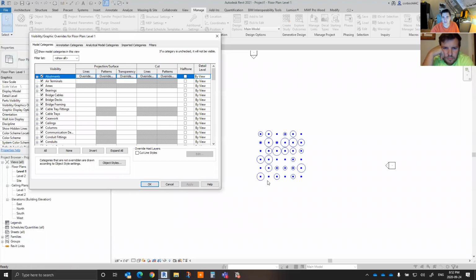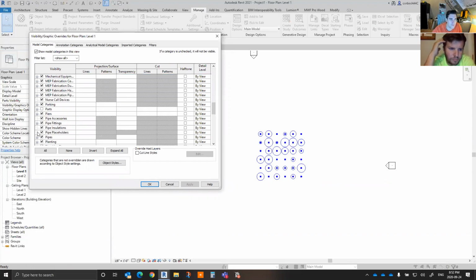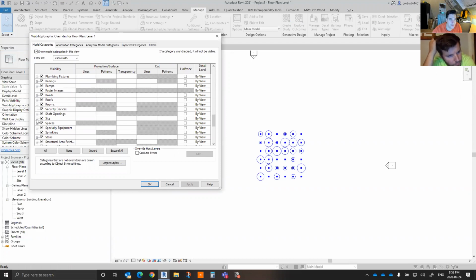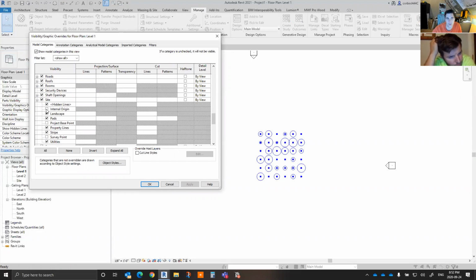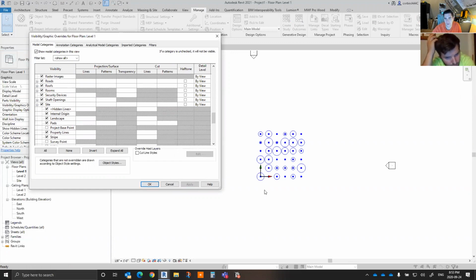You can see where this is starting, and it looks like it's starting right in the middle, but the point is starting right in the middle. The one thing you'll note from Revit, and this has been on newer releases, I think in 2019 or 2020 they started showing the internal origin. So you can see that this first point actually starts at 0, 0, and that's at the internal origin. The only reason I bring that up is that it's super helpful to understand when you're using Dynamo to model or alter something, so you understand where you're making that element. I'm just going to turn it off right now, but that's where it is.